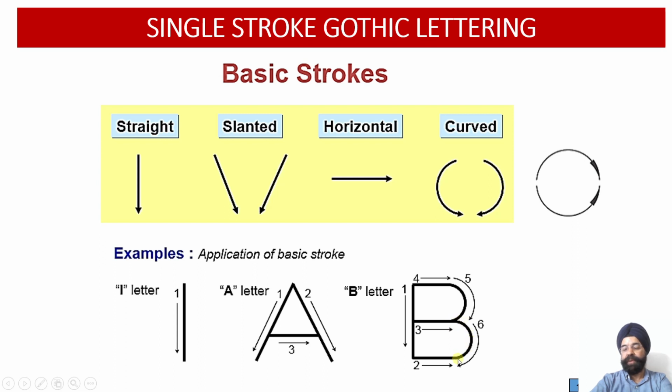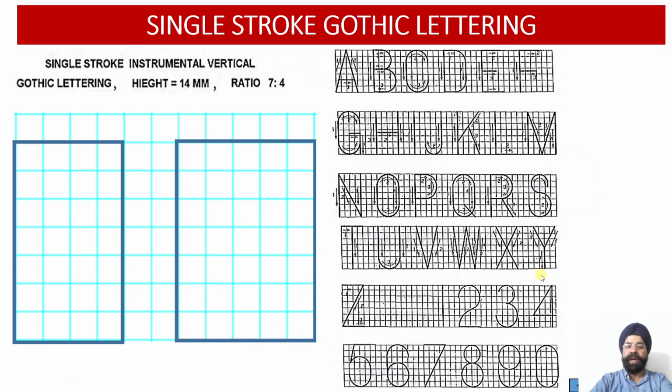Similarly, whenever you have to draw this, it should not be overwriting over there. So don't keep on overwriting your pencil onto the given space. So this is about 7:4. You can see I have got 1, 2, 3, 4, 5, 6, 7 blocks is my height. Then width 1, 2, 3, 4. So 90% of the alphabets will be written down in the 7:4. And the exceptions, they are W and M, which will be written down in 7:5.